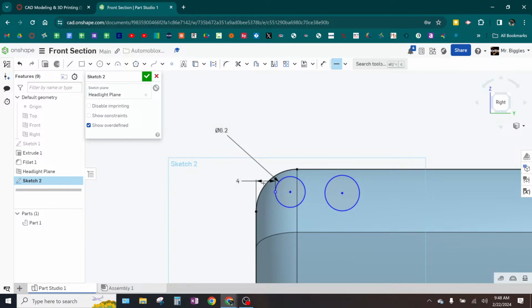But in practice, when you're reverse engineering, you typically cannot measure that distance. So when you make things in general, you won't do it this way. You'll dimension to the center of the circle. That's a very normal thing. But when you're reverse engineering, you have to do math to get that, right? And if it works, it works.